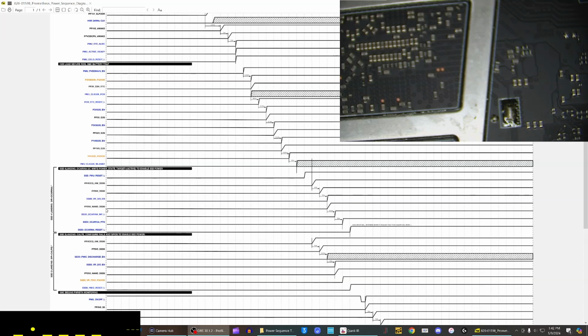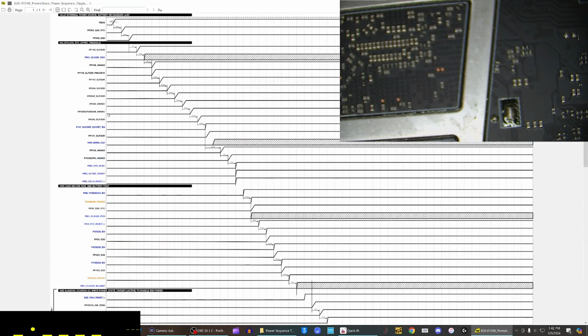Just for example, on a 16-inch A2141, a lot of times if it has a short like here, like that buck controller is shorting, you'll see 20 volts and like 0.2, 0.3 amps, like 6-7 watts. And this will just get hot. So you can just run power through USB-C and on a thermal camera see what's causing your problem, if it is a short that's causing your problem, which it generally is, right? But if we had a short on PP bus on that same machine, I would not see anything get hot through the amp meter, and I would get like 20 volts and like nothing, like 0.05 amps or something like that.